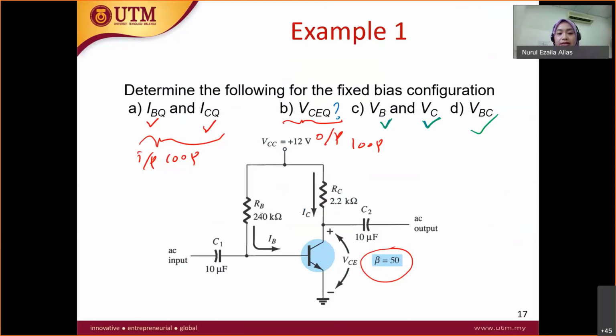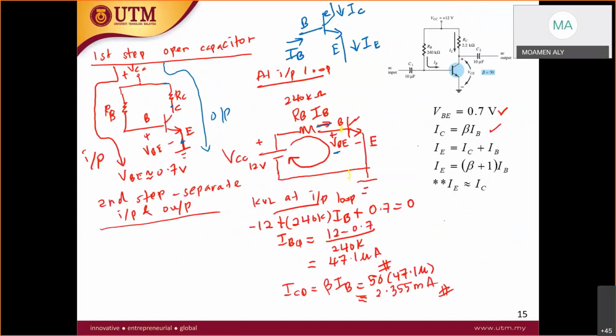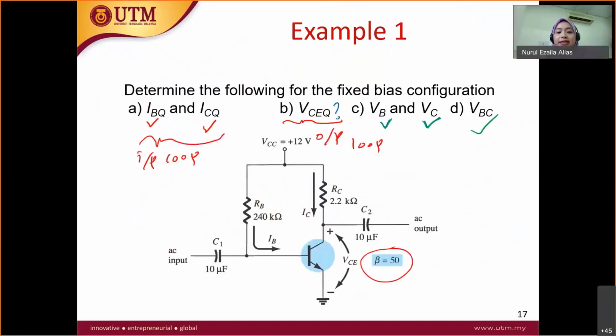Any question regarding this? So the capacitor there is for filtering or for what? The capacitor there is for filtering, but it will be used during AC analysis. Basically, this circuit is solving two parts, the DC part and also the AC part. For the DC part, every time we will open circuit the capacitor. We will consider the capacitor later, not in this part, later in part 3 or part 4.